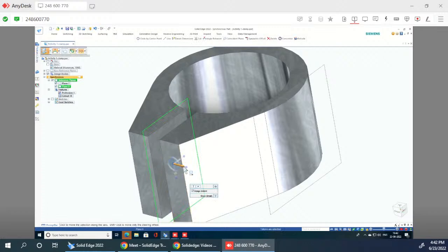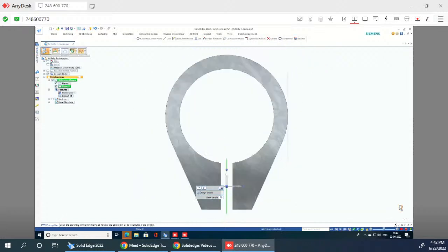Now click on this arrow. So you should click and leave it. Okay, you should not click and drag. Remember that. If you click and drag, then you will not get it. So just click once on this arrow and leave the button. Now you can see the plane is attached with my cursor. It is moving wherever my cursor moves, right? So at this point I need to click on this circle. Fine. So once the circle gets highlighted, click on it. So now the plane is exactly in the middle. So if you go to the top view, you can see that.